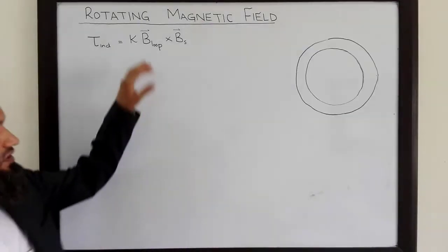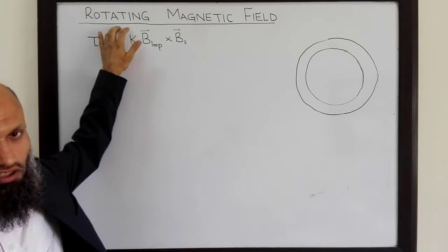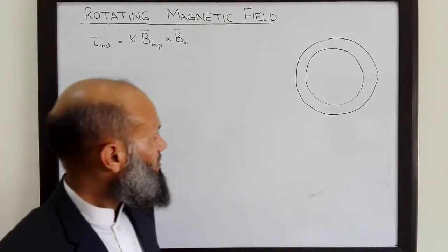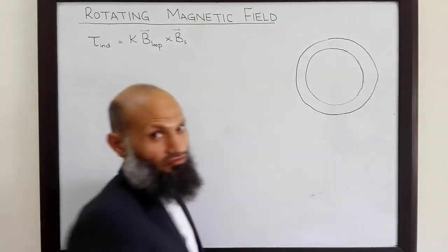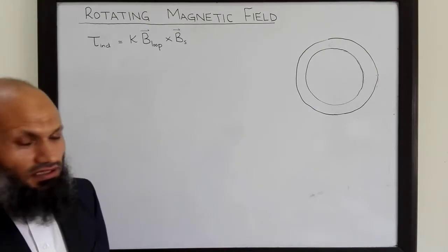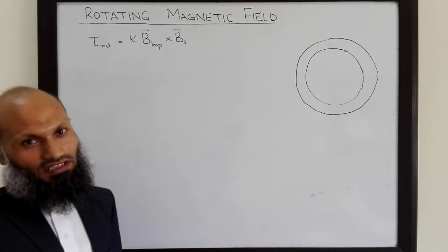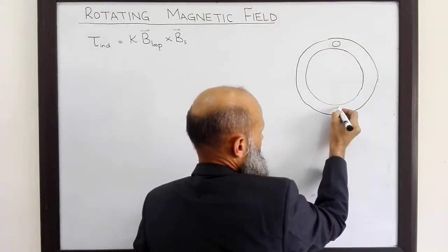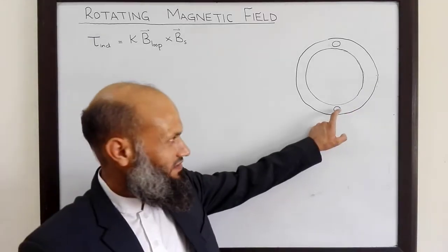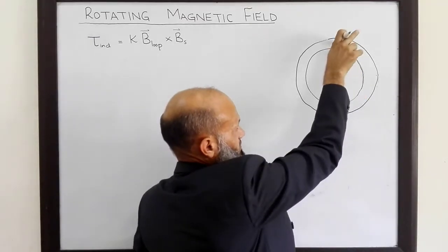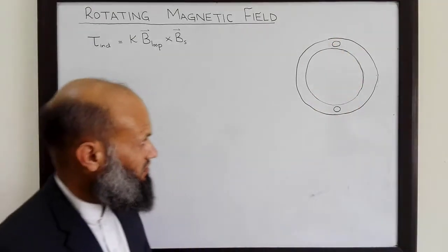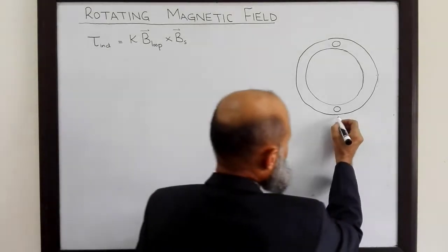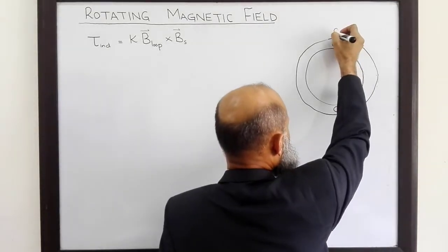In today's lecture, we shall talk about an arrangement which will create a similar effect as if the stator poles are rotating. The arrangement to create a rotating magnetic field consists of a stator. Here we have air space and a stator of ferromagnetic material. On this stator we wind a set of three-phase coils. The first coil is over here, with one side of the coil and another side of the coil. At the back end, these conductors are connected. Let's call this coil AA dash.